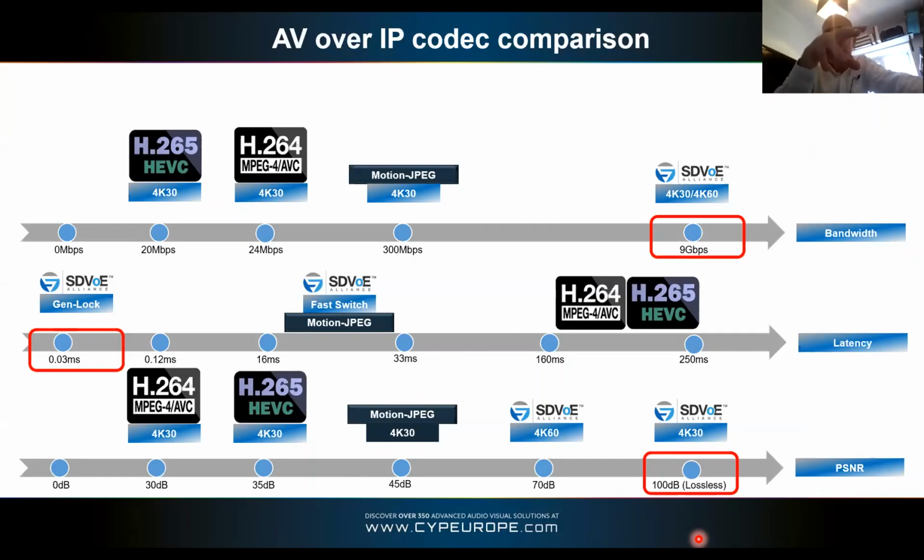What's also useful about H.265 is you can do a closed network streaming like IP or SDVoE, so a closed point-to-point TX to RX streaming matrixing system, whilst at the same time streaming it out to a streaming service like Twitch or Facebook or something. So it does have its uses, and we are looking at some technology at the moment that will help that.